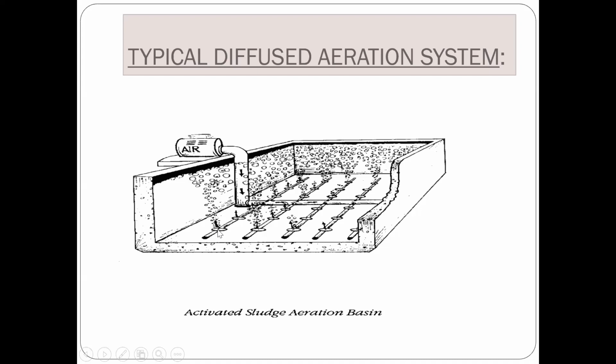Suitable nozzles are fitted to this compressed air pipe. Air makes contact with the water, and this process is carried out for 15 minutes. The theoretical detention time of air mixing is at least 15 minutes.